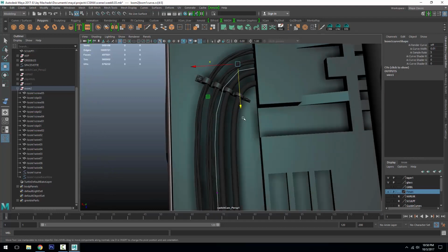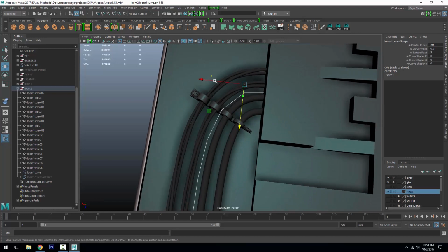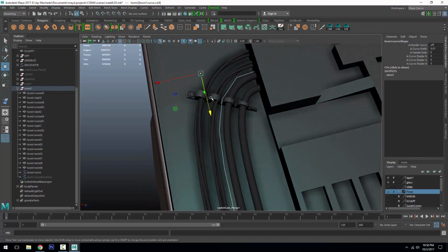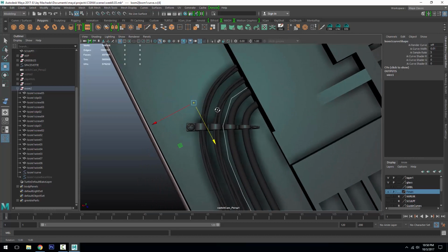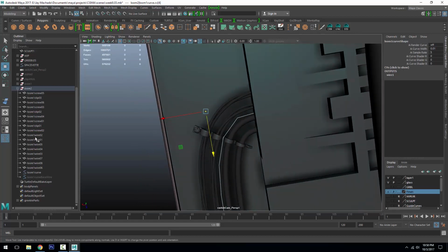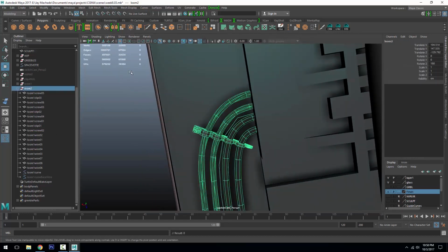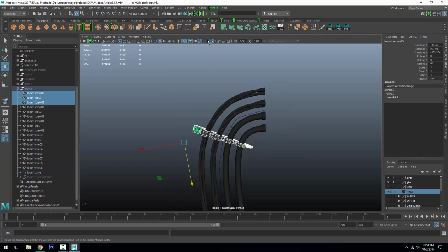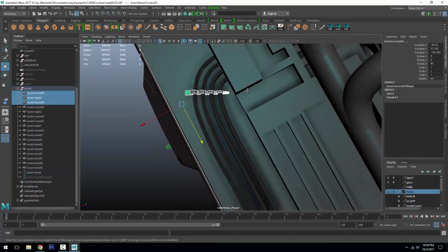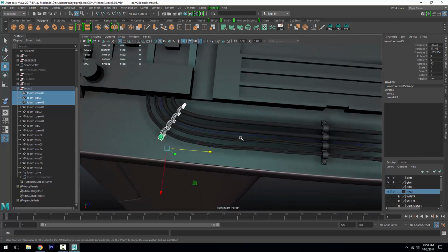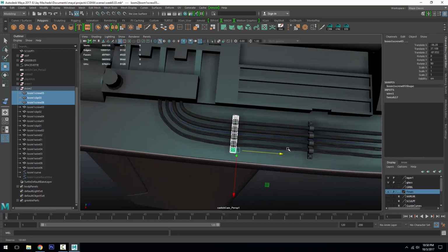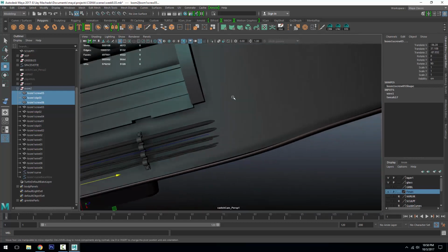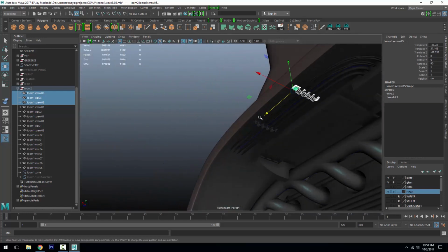And you'll notice how, as this curves around, this piece is kind of getting this weird sheared shape on it. So let me grab this and isolate it, and then I'll just select that piece. And what's cool about the wire deformer having kind of a live history to it is I can just drag this down until it straightens out again, and then we have that clip there.